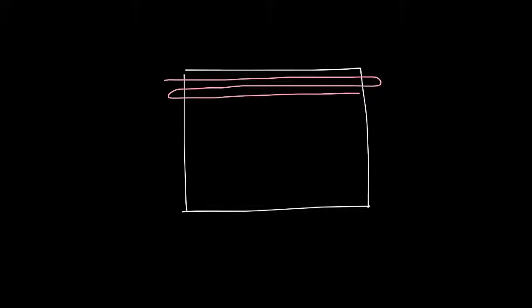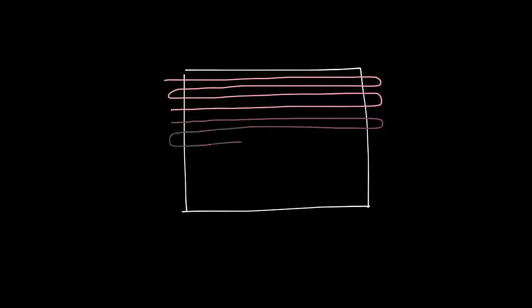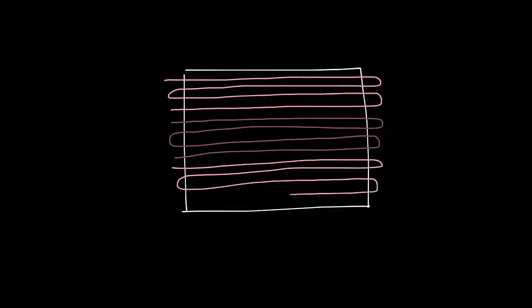So let me draw a side view of this water coil. So we'll just show the circuits going back and forth in the water coil. And I'll draw the second circuit in a slightly different color just so you can see the difference between all 3 circuits. And then we'll draw the third circuit. So we'd have water entering the water coil at the bottom of each circuit, here, here, and here.